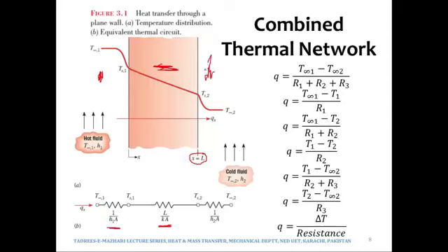And on this side we are also having convection. So we have convective resistance between Ts2 and T infinity 2, which would be given as 1 over HA, meaning 1 over H2A. So they have taken H1 and H2 as different. They may be same, they may be different depending upon the conditions, the type of the fluid, the velocity of the fluid, the temperature of the fluid, etc.